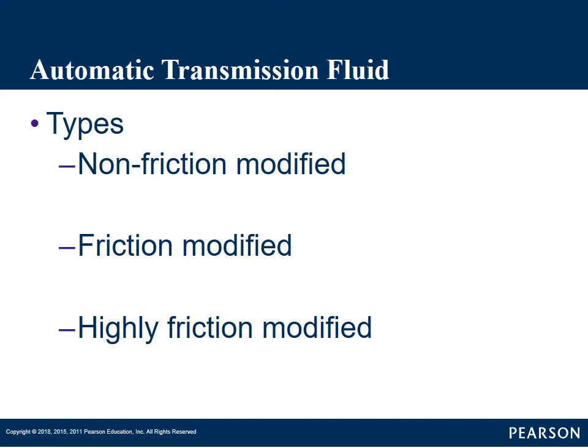If you're accelerating real hard, you can just do what we call dumping the clutch, burn the tires off, and take off. The principle behind letting it gradually, it slips a little bit, but it makes a nice gradual engagement. If you just hit really hard, it would shift real hard, and customers would complain.